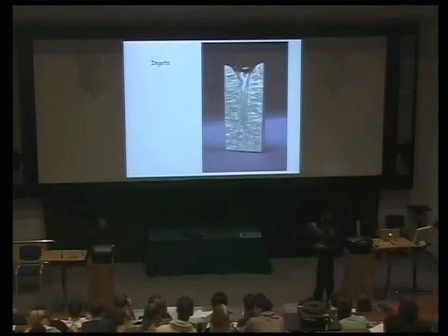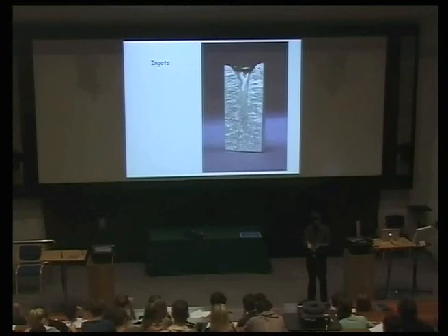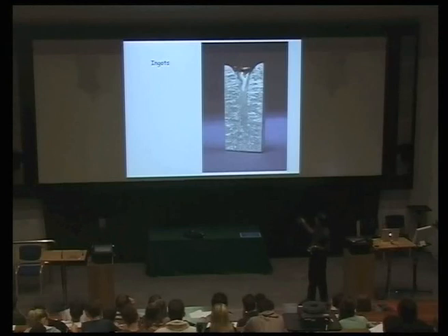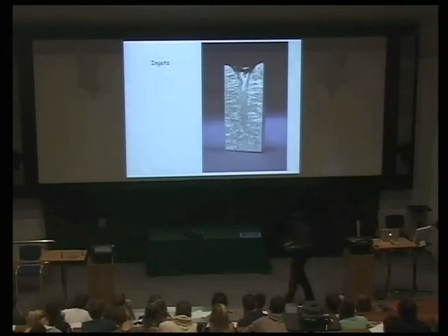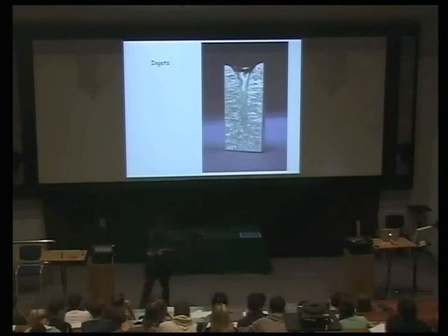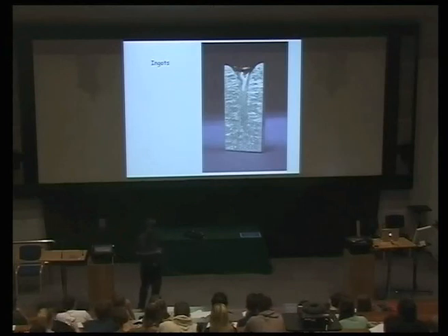Okay? This pipe is because when the liquid freezes, there is contraction, and therefore, even though you fill the mold up to here, you will end up with a hollow, and you have to cut this off, and that's a waste of material. So later on, in this series of 3 lectures, I'll show you a process which completely avoids this problem, and that is the process which is used in mass production. Completely avoids the problem of this pipe here, which comes from contraction.